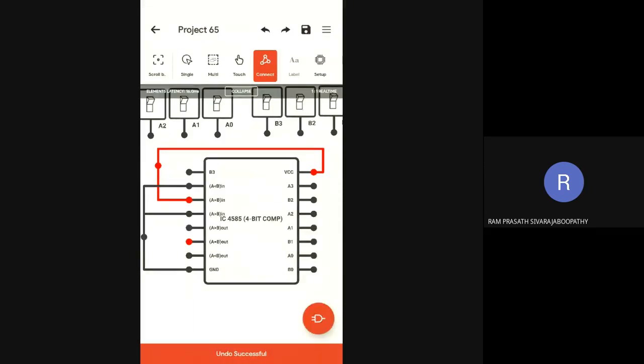Sir, if we connect neither 0 nor 1, then what will be the condition of the pin? See, it should not be left open. If you leave it open, you will get improper output. Clear? That is the condition we must follow. If you don't follow it, you will get random, unexpected output. You can see it in the datasheet also.